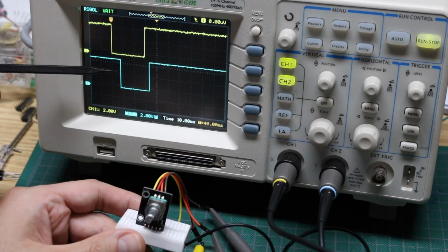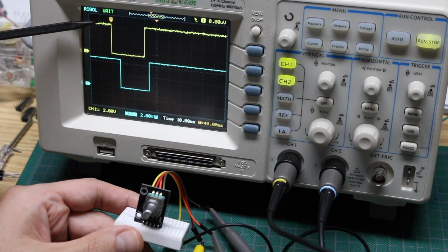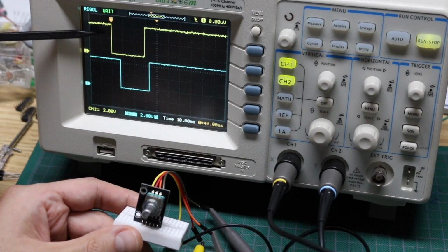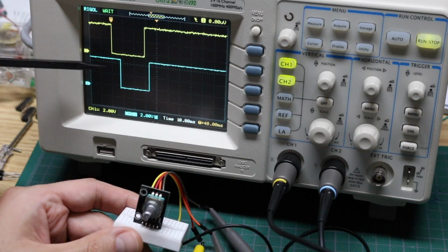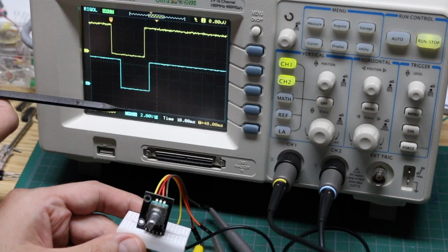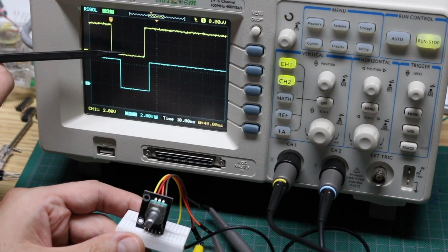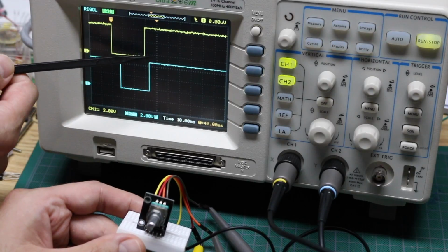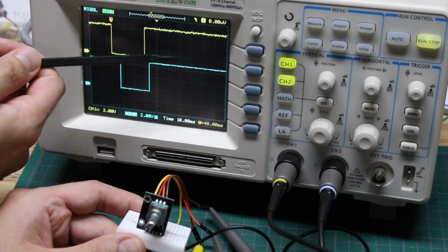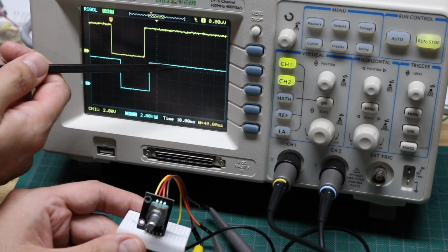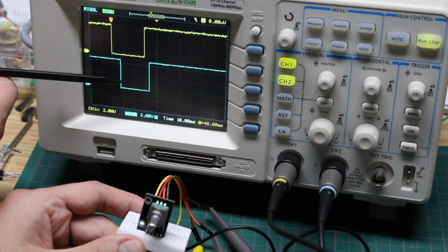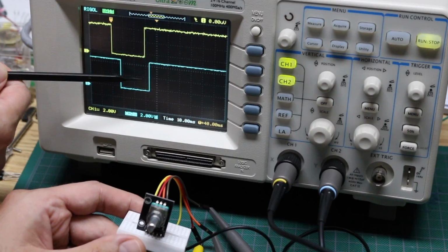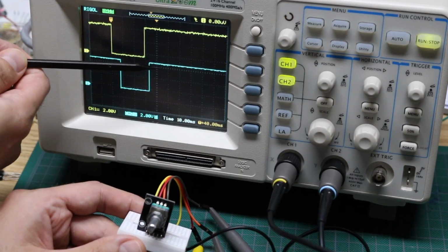What we need to do is detect basically which one went low first when they're both idle, and if it's A that went low first, it's clockwise. If B went low first, it's counterclockwise. After we've detected this, which we can do from this opening portion, somewhere around here before we go back to being idle, waiting for another rotation, it's a good idea to generate our output signals to say what we've interpreted before this goes high again.